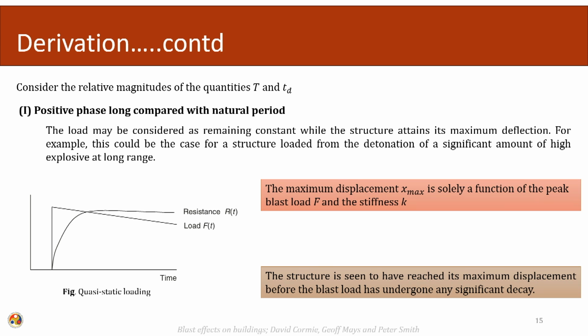So, we can also consider the relative magnitude of the quantities T and Td. The case where the positive phase is long compared with the natural period. The load may be considered as remaining constant while the structure attains its maximum deflection. For this example, there can be a case for a structure loaded from the detonation of a significant amount of high explosive at long range.